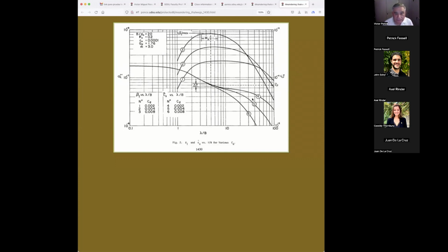And the celerity. Celerity was an interesting concept because celerity is the velocity of the wave. And we were talking about the bed wave, not the wave like you would imagine a water wave. No, this is not a water wave. This is a sediment wave. It's a bed wave. But the calculation allows you to, at the same time you get the celerity, also get the amplification. Amplification or attenuation. In this case, it was amplification.